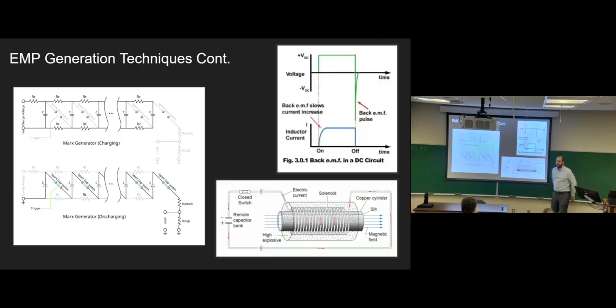Yeah? Are those capacitors in series? The diagram would have me believe that. Here they're in parallel when the spark gaps are open, and then the moment the spark gaps close, they all go in series. Wouldn't that be reducing capacitance though? It reduces the capacitance, but the overall energy is amped.